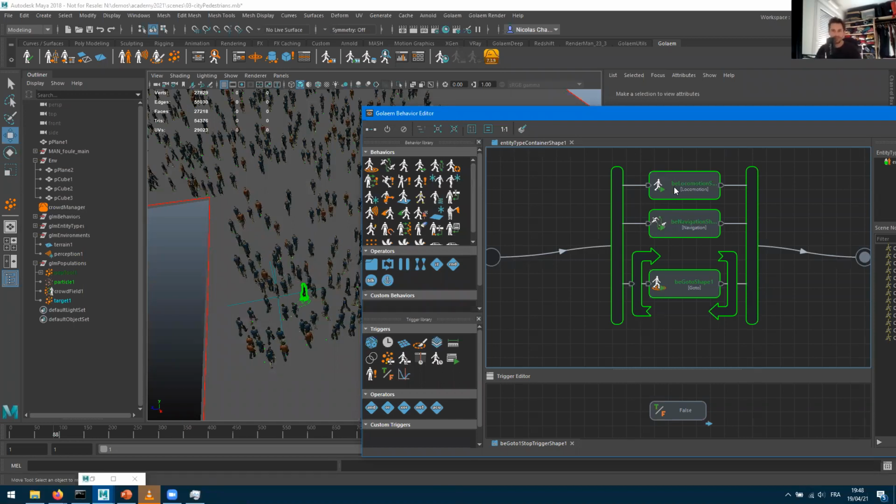So navigation speed, increase speed. Yeah, you guys are better than my regular students. Usually they go into the locomotion and look for a speed parameter and they couldn't figure it out. And obviously it's not here, because the locomotion will just follow what it's asked. It does not generate any speed or any velocity. That speed or that velocity comes from the navigation.